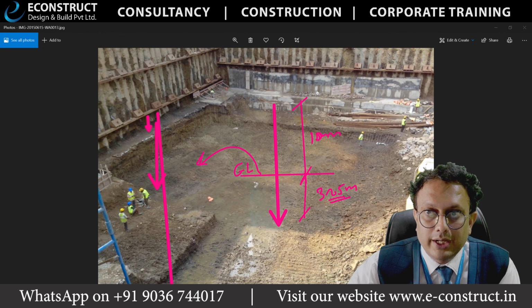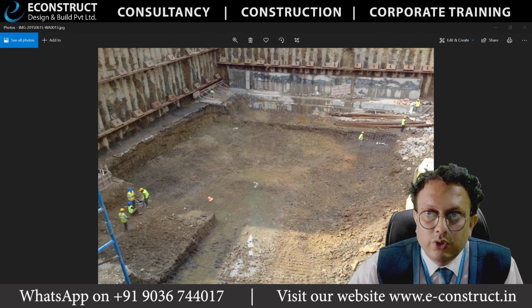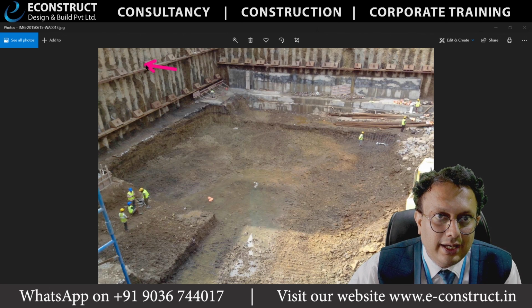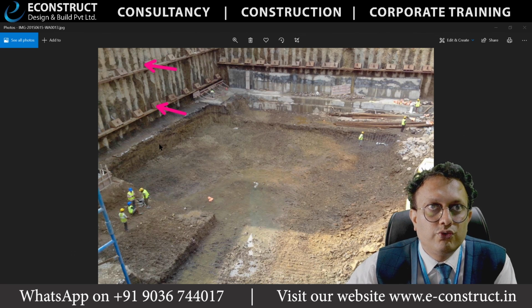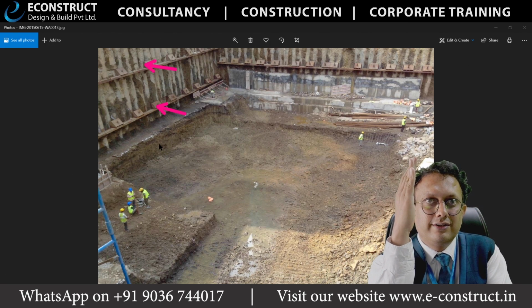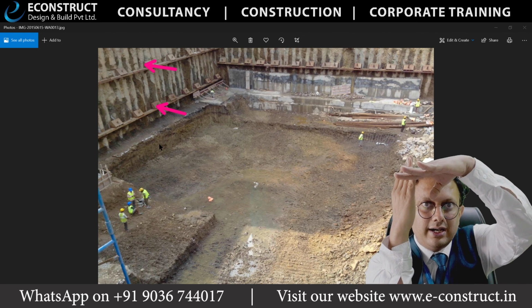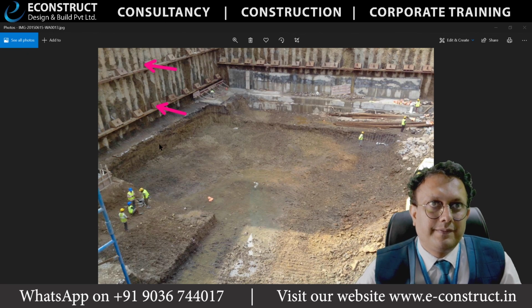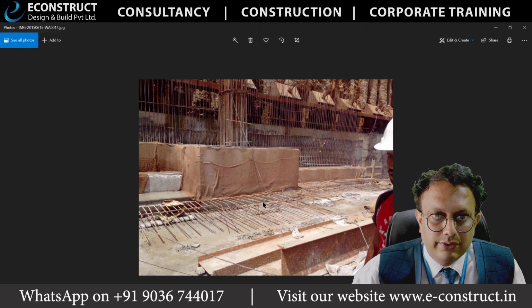So this is how actually you need to develop the system. Why two phases? You are having an anchor here and you are also having a PT strand here. In both cases, two phases of PT strands, because it's a cantilever, right? Okay, so I am giving an anchor here and also an anchor here, so that it will not come down. So this is how you need to start learning the different features.